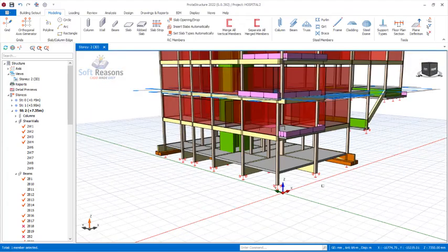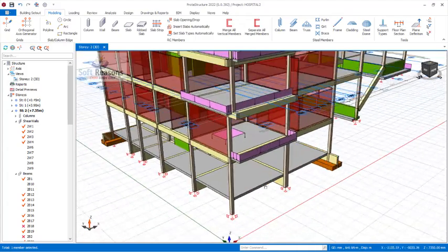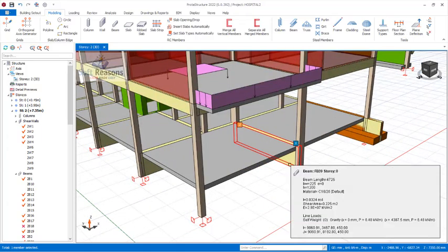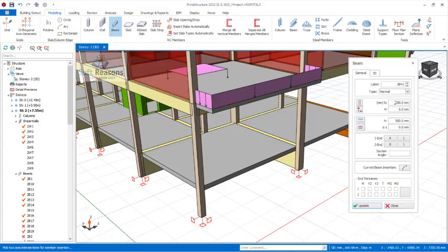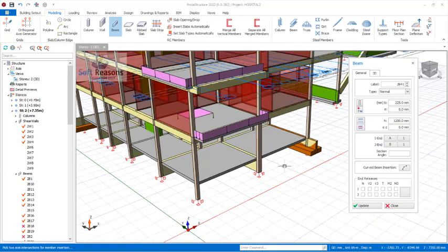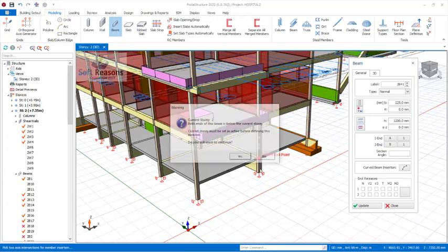Now you can see all of here is being opened. What you have to do first is to place the beam. I'm already having a beam. You can see the depth of this beam is 1.2, or you can come over to where you have your beam member, and then you give it a thickness of 225, and then the depth is 1200 millimeters, just like this. After which you will proceed, I pick the first point all the way and pick the second point right there.